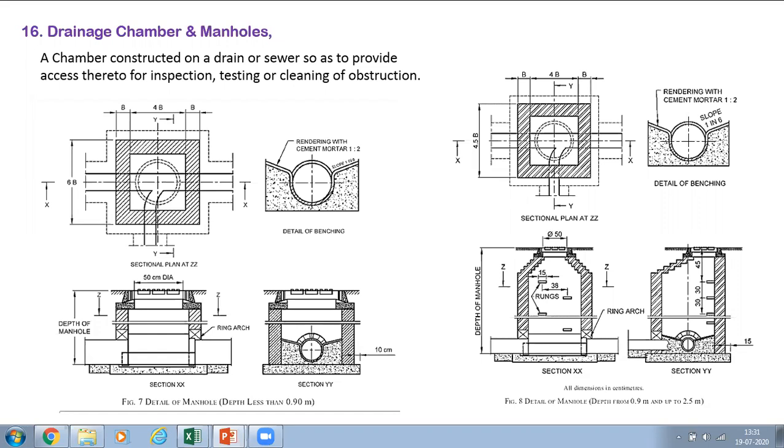The pipe will not get damaged. Suppose there are cars, trucks and other vehicles, then from the top of the pipe you have to give 1 meter depth. Minimum 1 meter depth you have to give in the heavy vehicle movement area. If there is no vehicle movement, only cycles or people going there, then 600 mm, that's all. That is the depth scenario.